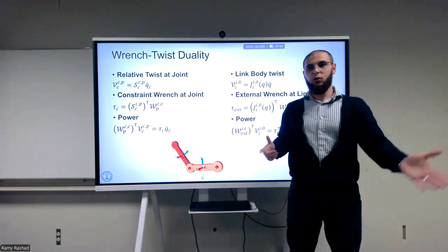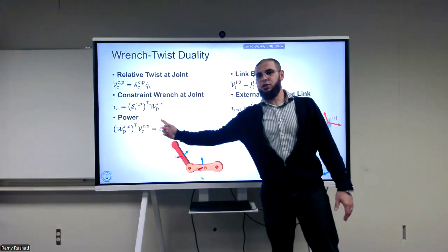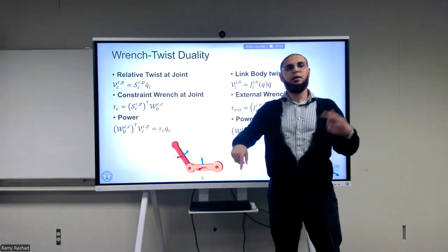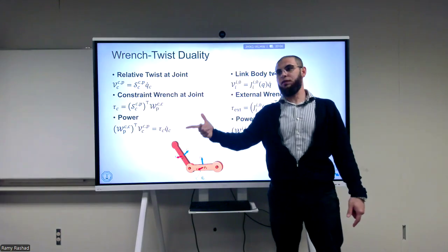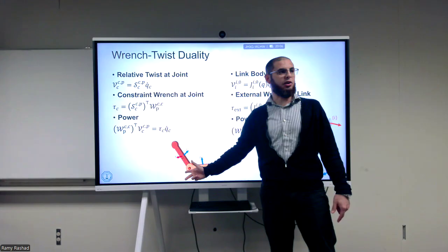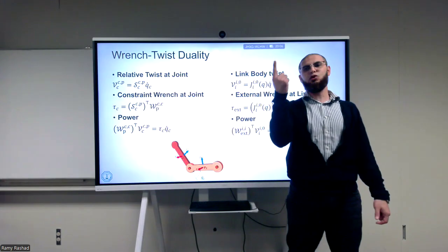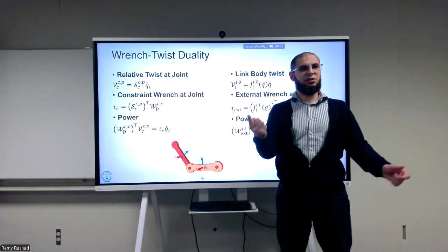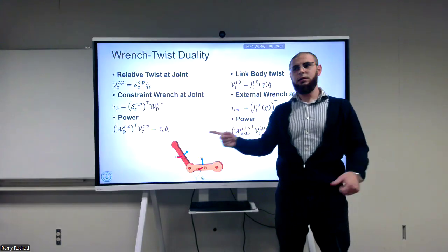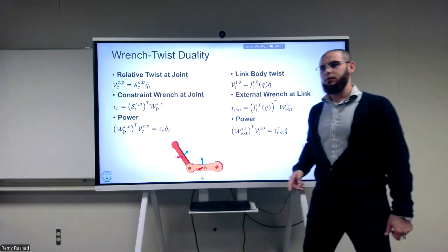It's constrained, which means that you cannot have any actuation force in this direction. The same is true in all of the three forces. All of the translational degrees of freedom are prevented by the joints. You remember what we said about the joint, that if it allows B degrees of freedom, it constrains 6 minus B? That's exactly the idea here.